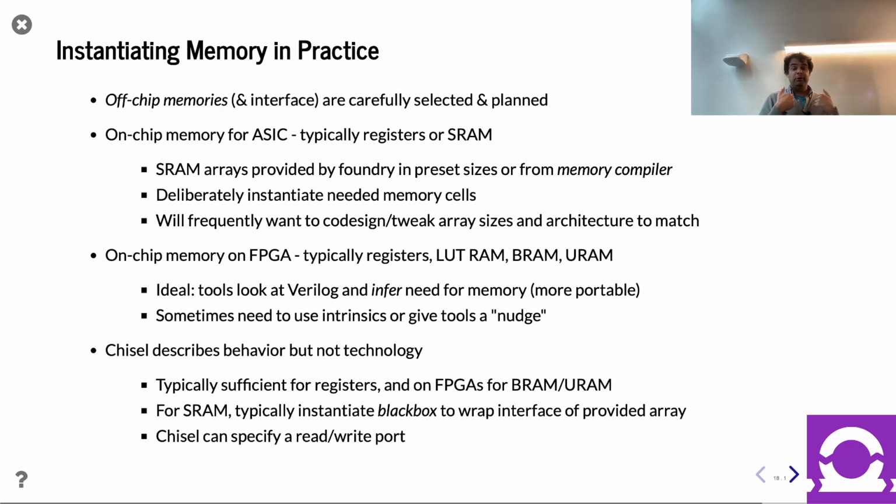And in my research group, we use FPGAs quite often with designs that originally started in Chisel, and we care about performance, so we'll look down at how they were mapped. We often find that our memories, this exact same component just instantiated multiple times, we've seen it instantiated as LUTRAM, BRAM, and registers in the same design, right? So tools will make those choices ad hoc as it makes sense. And so give it the opportunity to do so.